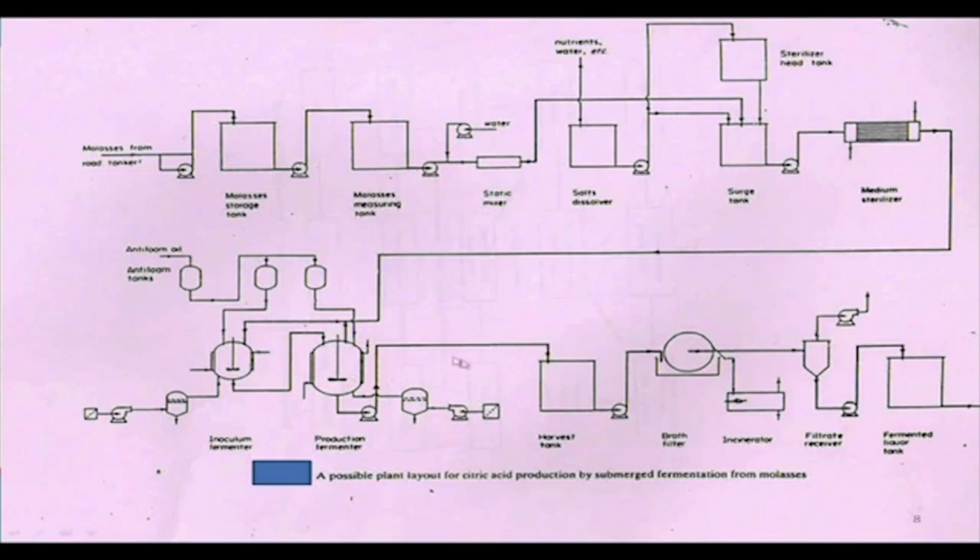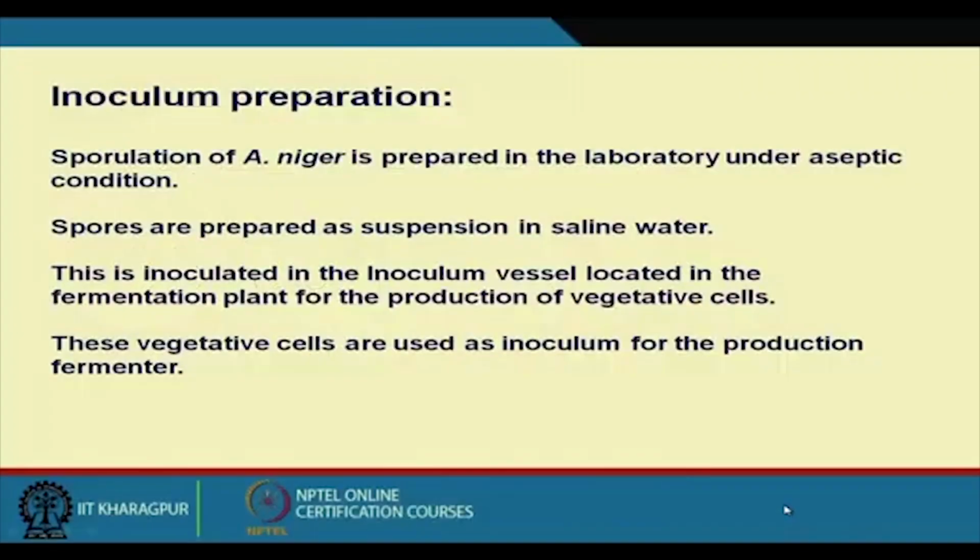After the fermentation process, the cell mass is an impurity in the reaction mixture. So you have to remove the cell mass first by using the rotary vacuum filter, which I shall explain in detail. Then you take that filtrate out and put it in the filtered reservoir, and you put a vacuum so that the air content is low and oxidation doesn't take place. Then further purification takes place. I shall discuss that later.